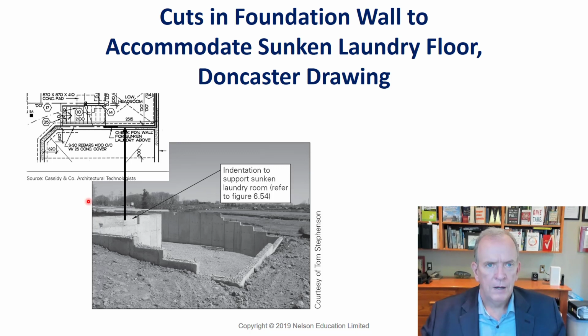So when we talk about foundations too, foundations aren't typically smooth. They can be stepped. We talked about stepping in the last lecture, so the grade is stepping in this case. And in this case too, you've got a wood frame floor that's going to go into this area here. There would be a sill plate that would be placed here. We'll talk about this more when we get into framing, but you have to form this out.